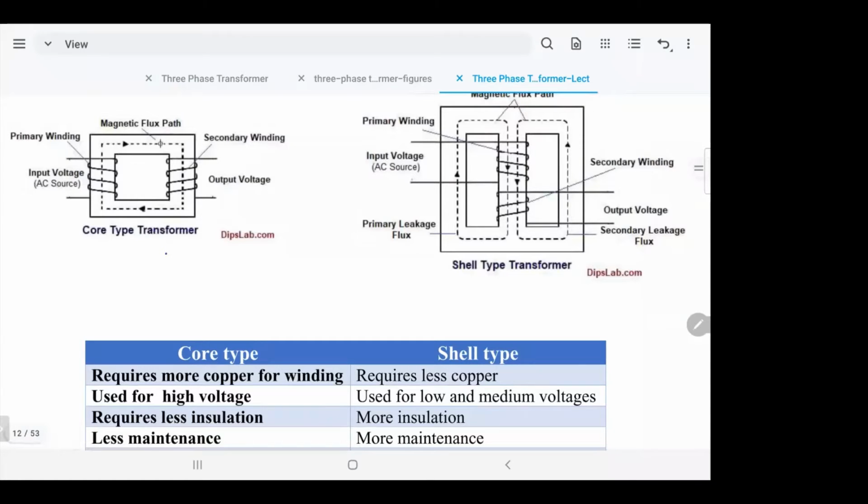Plus something you will learn about when you study power, which is called third harmonic. If you studied series in signal processing, any voltage can be decomposed into a series of sinusoids with different amplitudes and frequencies. This happens when you have distortion in the waveform. If you don't have a smooth sinusoid, and that's inevitable, it happens all the time, you will have distortion in the voltage, because the load we usually use is not a linear load, it's a non-linear load.